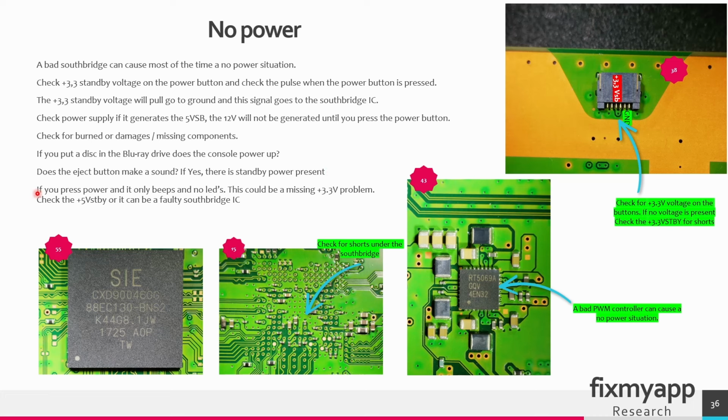If you press the power button and the console only beeps and you don't see any LED indication, this could indicate a missing 3.3 volt. So check if the 3.3 volt is present.